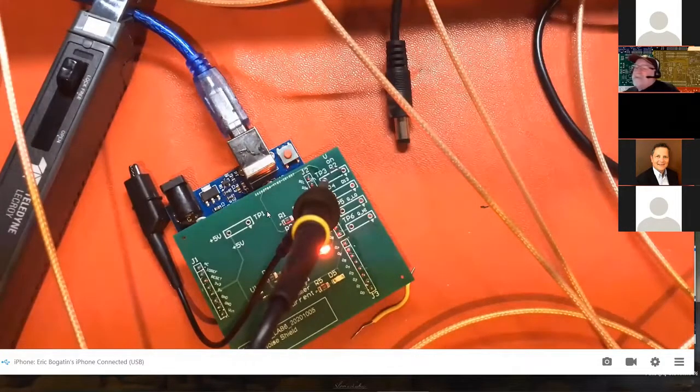And so with the bandwidth of 4 gigahertz for the REL probe, the 2 gigahertz in the WaveRunner is a little limiting. That's why I tend to use the REL probe with my WavePro HD scope, which is an 8 gigahertz bandwidth scope. The differential amplifier, the one I have here, our older one, is only a 500 megahertz bandwidth, where the 1 gigahertz bandwidth of the scope is valuable.